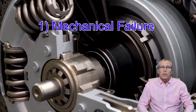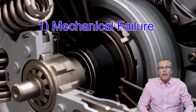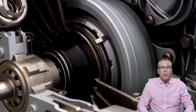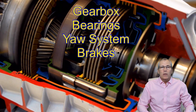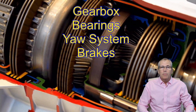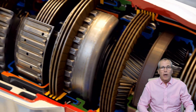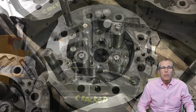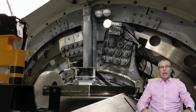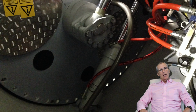Number one on the list is mechanical failure. Wind turbines have many moving parts that can break down or wear out, leading to costly repairs or equipment replacement. Common examples of mechanical failure include issues with the gearbox, bearings, yaw system, and brake system. Gearbox failure is one of the most costly and frequent mechanical failures, as it can lead to damage of other components and downtime for the future.